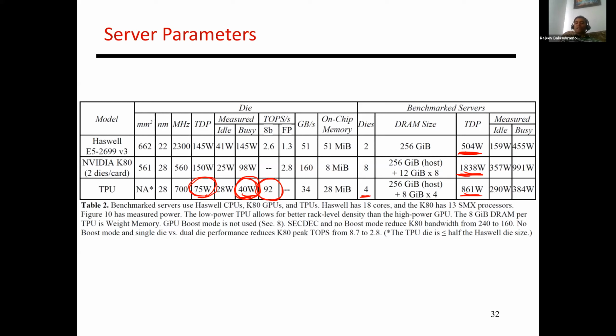So a question about, I guess, the Google TPU and whether the weights are pre-stored in the array. They are not stored permanently, right? When you're doing a certain layer, I need to get the weights for that layer. And so there's a prefetch operation that tries to bring in the weights while you're working on the previous computation. Once that computation finishes, you use those weights, and hopefully you're busy for many cycles.